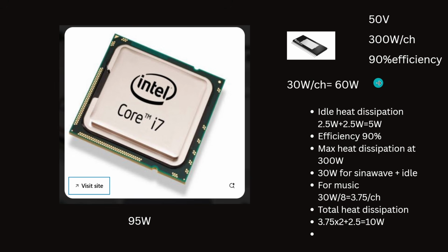Impossible at any rate, and we don't need it for an audio amplifier. One more thing, idle heat dissipation. The chip is not 100% efficient, and we have losses. Typically, when you just switch it on and there is almost no music, we still have 2.5 watts at the chip level, and about 2.5 watts at inductor level, so minimum 5 watts. In reality, the whole board has even more watts to dissipate.